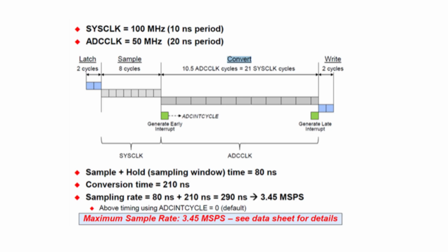What if you need both speed and accuracy with a tricky sensor? That's often where external circuitry comes in. A common solution is to put an operational amplifier, op-amp, configured as a voltage follower, a buffer, between the high impedance sensor and the ADC input. The op-amp has a very high input impedance, so it doesn't load the sensor, and a very low output impedance, perfectly capable of driving the ADC's sample and hold capacitor quickly.